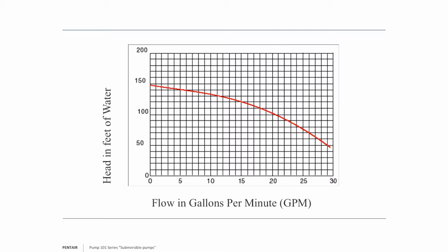And one question I always get is people ask me, well, why at 29.5 gallons per minute? That's run out. You're no longer producing any more gallons per minute than that. Why does it not go to 0 feet of head? And the simple answer is because at full run out, it's still producing pressure. So we have to show that. We have to reflect that upon the curve.